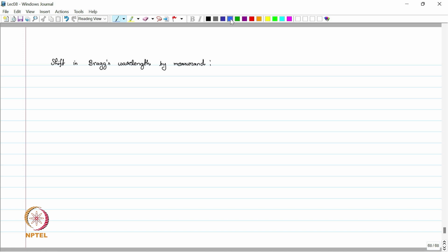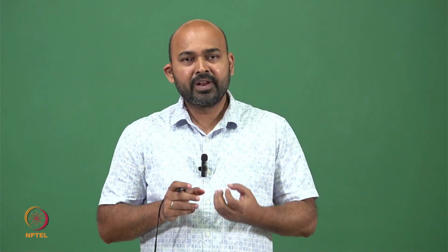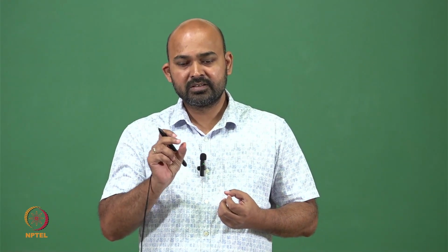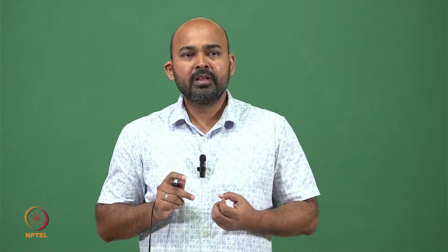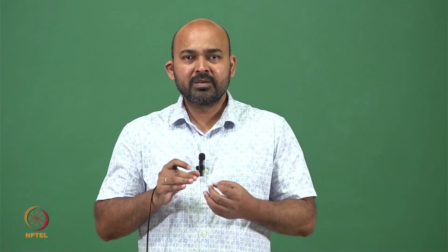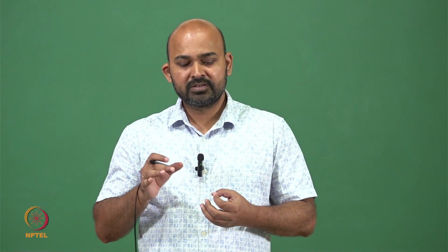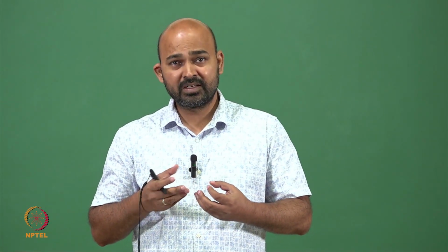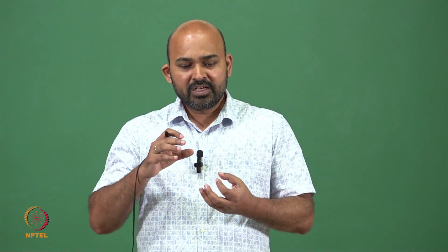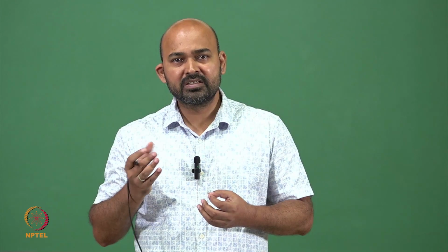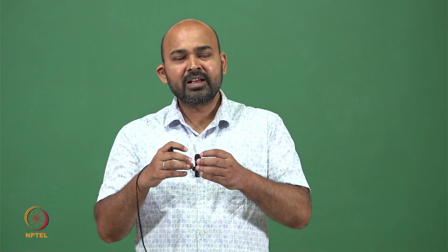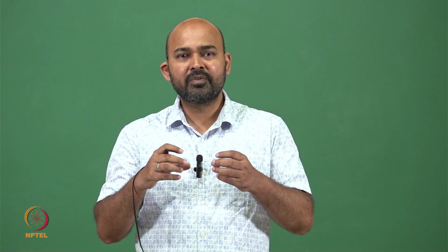So this particular wavelength is reflected by this grating, which has a constant spacing in between. Now this spacing we can subject to the measurand. So for example, we want to measure the temperature. When we expose this grating to the outside temperature, let's say that temperature is higher, there will be a thermal expansion in the optical fiber.